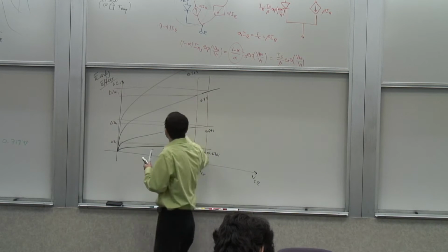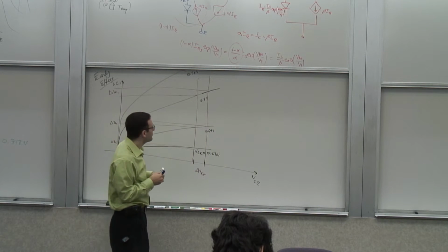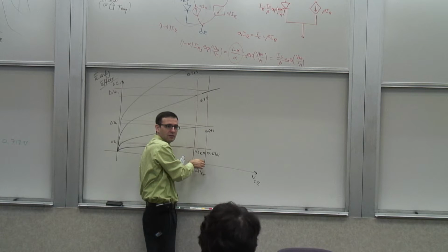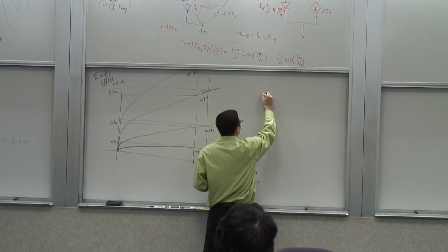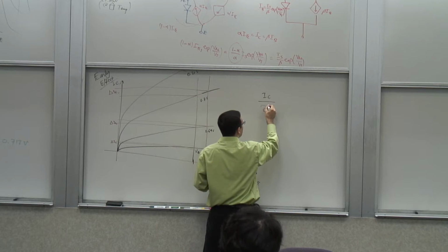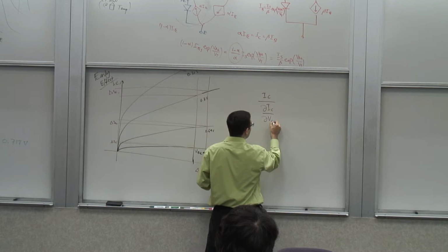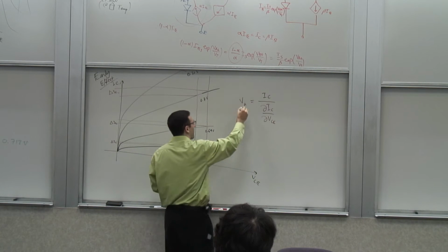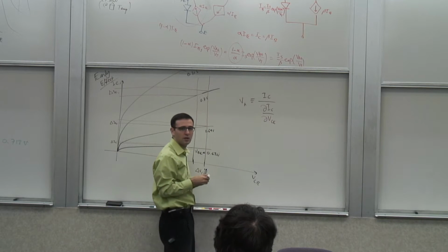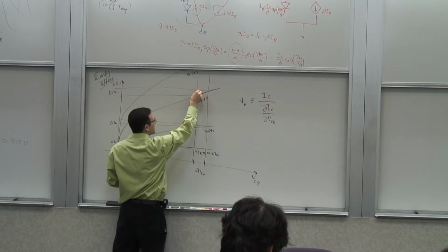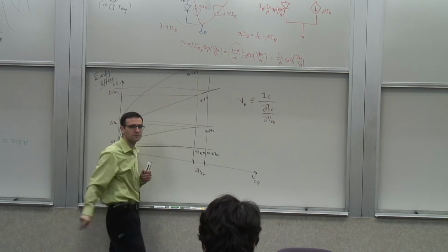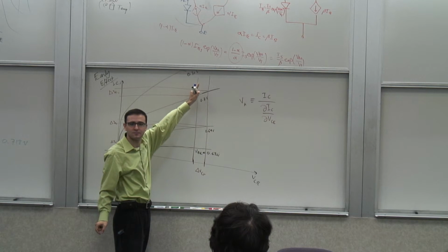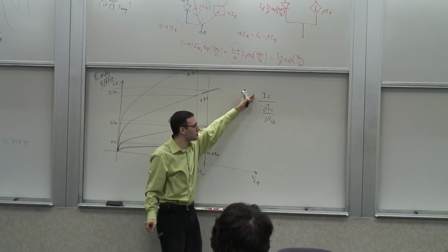So what is the quantity that's kind of constant? It's the ratio, really, of the net current to the variation in the current due to the voltage, right? And therefore, we can define this quantity that to first order should be constant, IC divided by dIC/dVCE. It has units of voltage, and we call that the early voltage, shown as VA, right? It's the ratio of the absolute current to the slope. The higher the absolute current, the smaller the slope is. So it keeps the fractional change constant.